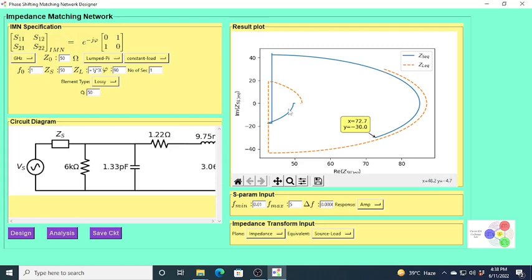And you can see in this thing, basically the load point. So, basically the load at the source point, the equivalent load impedance is supposed to be 50, but due to this loss element I am getting a 52, and this is coming as 0.4. So, I am getting some additional thing in the resistive part, the 2 ohm additional thing. So, that basically leads to some kind of losses.